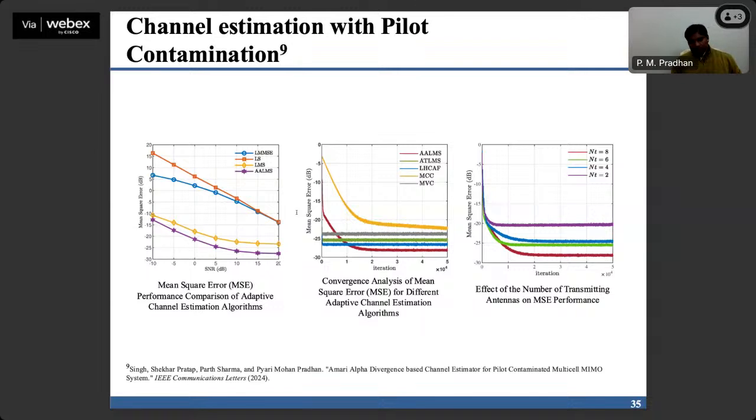Okay. Now for estimating these parameters, what we do in general in wireless communication is you send some sets of pilot signals and you receive those pilot signals. Of course, these pilot signals will go through the channel, so there will be some attenuation, there will be some disturbances, there will be some noise added to the pilot signal. So when you receive those pilot signals at the receiver, you use these noisy pilot signals along with the original pilot pattern to estimate the channel.